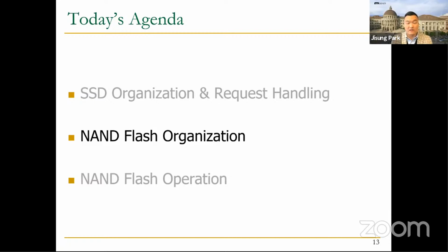There are some spare cells along with the page, and we'll cover this very soon in this lecture. Anyway, there are some spare cells to store such dedicated metadata for specific data, which is called the OOB, out of band area. So basically the answer is yes. The parity should be stored along with the raw data at the same position.